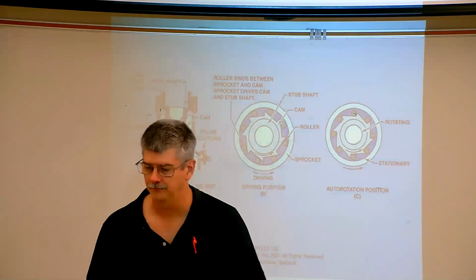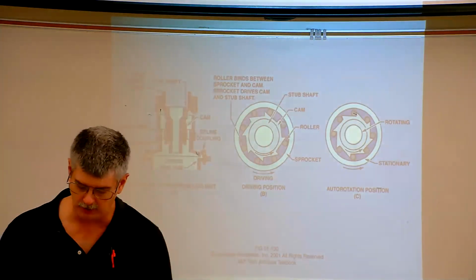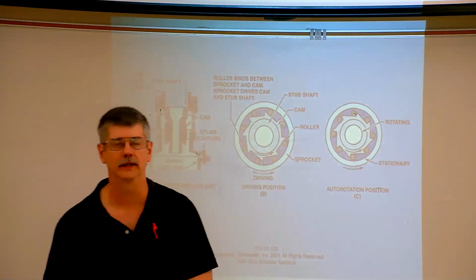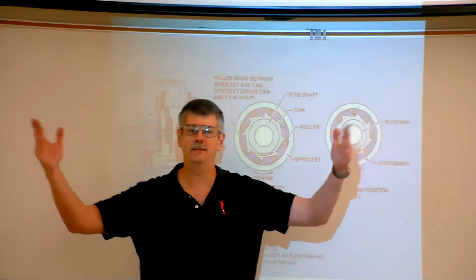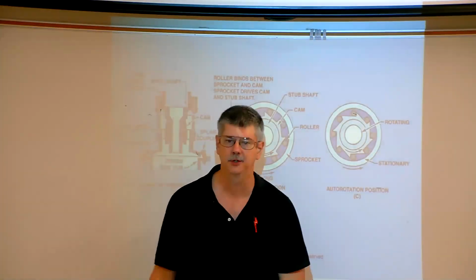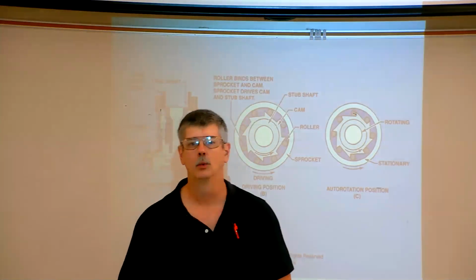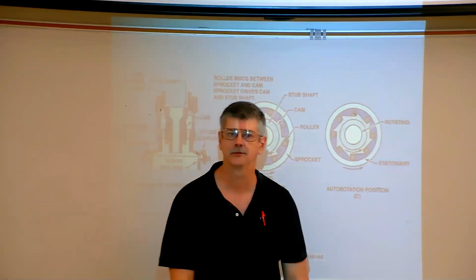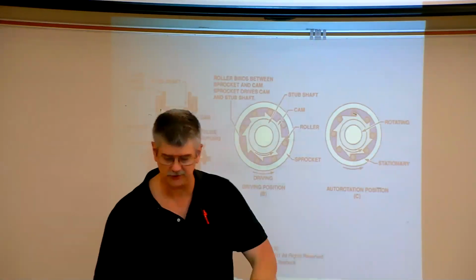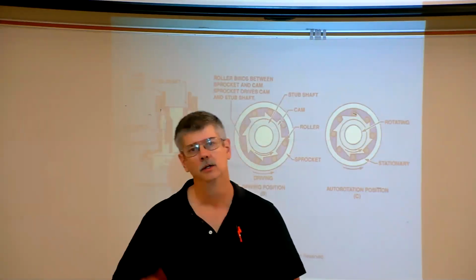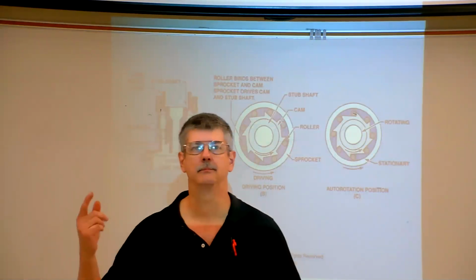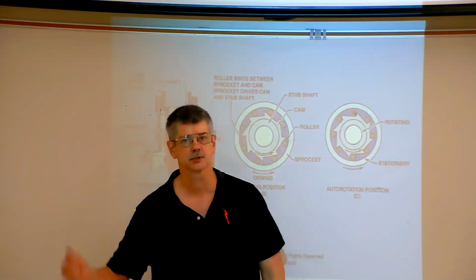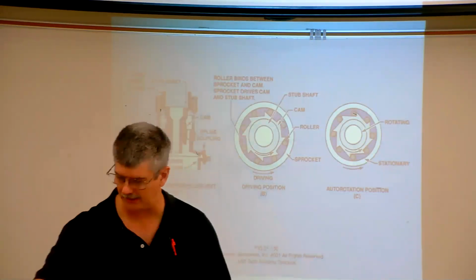All right, with that, I do want to review, and I'm going to try to do it kind of quickly. Going back from page 1, we have 2 types of aircraft construction: the truss type and the stress skin. 2 types of truss type structures: Warren and Pratt. 2 types of stress skin: monocoque and semi-monocoque. Out of the 2, which one has a substructure? That is semi-monocoque.